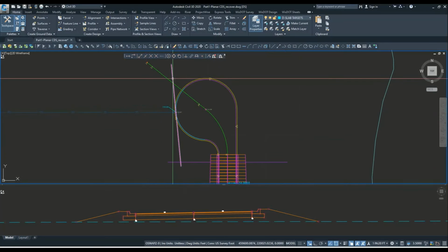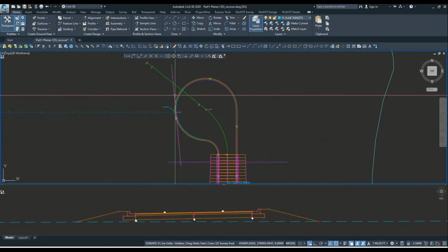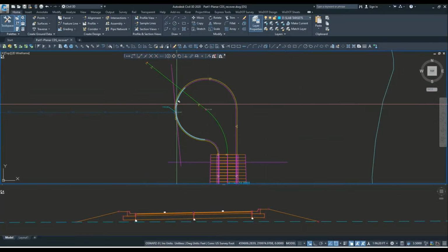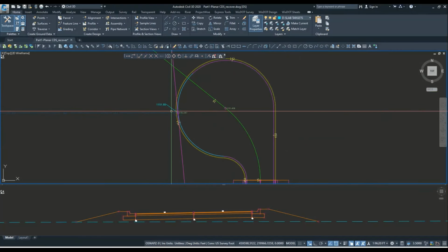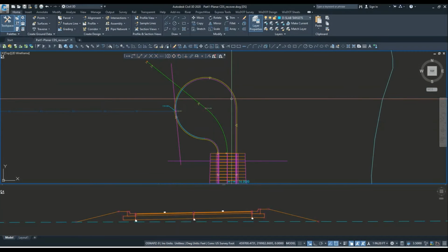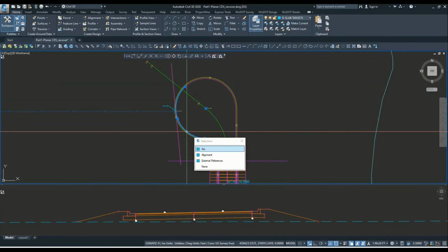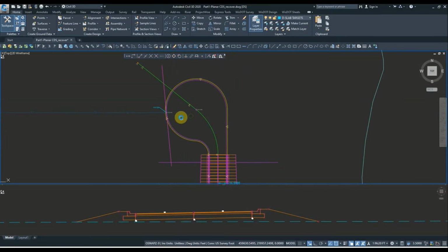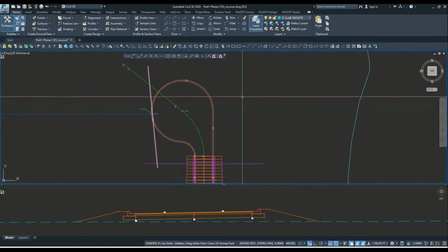So what this feature line represents is what we'll be grading from for the rest of the cul-de-sac. So then slowly we'll be going from 1151.60 to whatever elevation we need over here. First off, I'll delete this, we don't need it anymore. And I'll go ahead and grade.